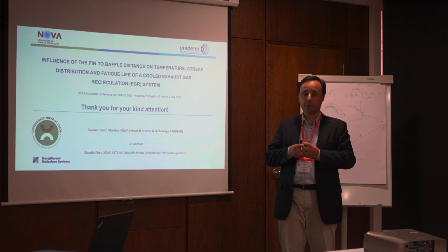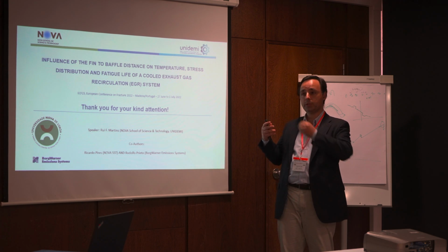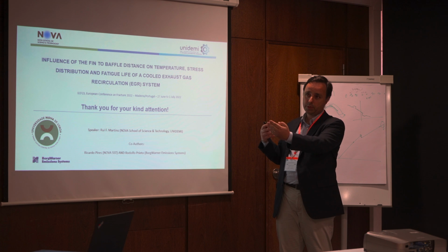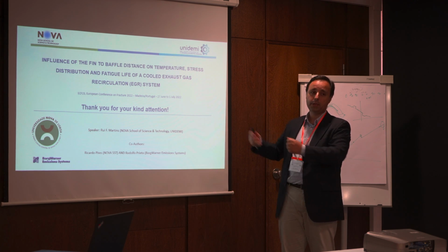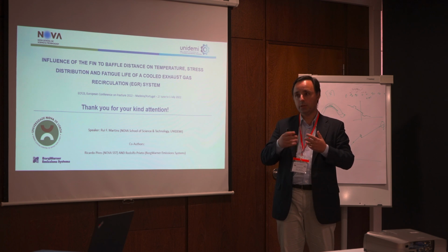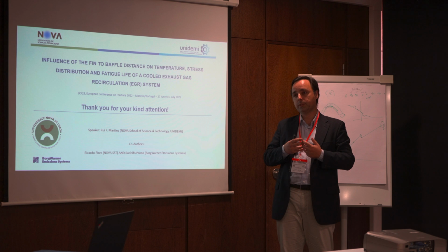Thank you very much for the question. It's very difficult to find parameters for the Coffin-Manson equation for those temperatures. And there's another difficulty because we have temperatures that range from 600 degrees Celsius to 300 degrees Celsius. So we have searched a lot of parameters and we have used those parameters for the Coffin-Manson.